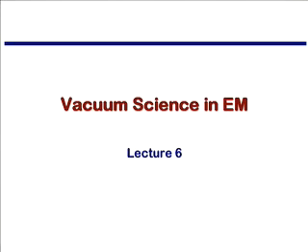Okay, so when we talk about the microscope, one of the most important things is that we have to do all this in vacuum. And it's been my experience in introductory level and even beyond in the TEM and in the SEM2, which is the next class you may take, most of the problems people have are to do with vacuums, right? Getting the sample in and having the vacuum crash. Having stuff come off the sample and the vacuum crash. Having the vacuum crash because of a problem.